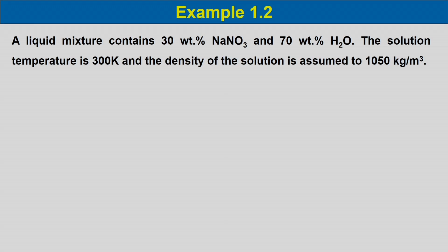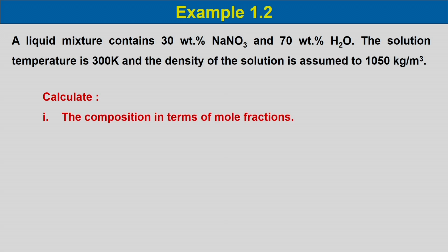Let us take another example. A liquid mixture contains 30 weight% sodium nitrate and 70 weight% water. The solution temperature is 300 Kelvin and the density of the solution is assumed to be 1050 kg per meter cube. Now, we need to calculate the composition in terms of the mole fraction and the total molar concentration.